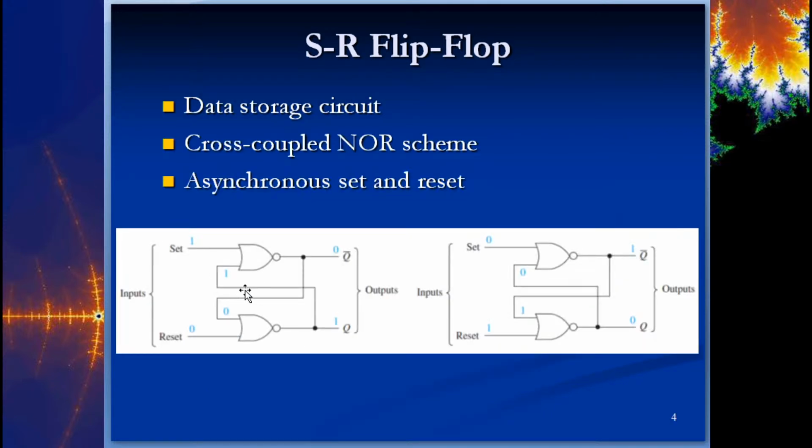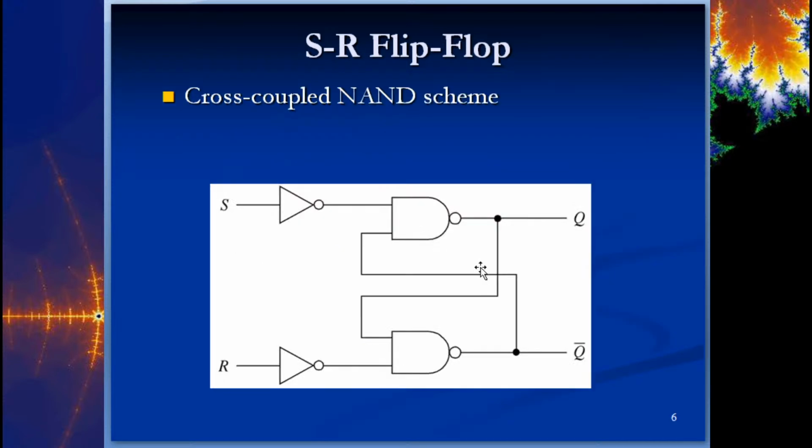So you can see here in the cross-coupled NOR, there are no inverters. There's only 2 NOR gates. That's it. And so if you have set on top and reset on bottom, these are going to be flipped, right? Q is down here on the reset, and Q naught is up here off the set NOR. But when you come down to the cross-coupled NAND, it's flipped, right?